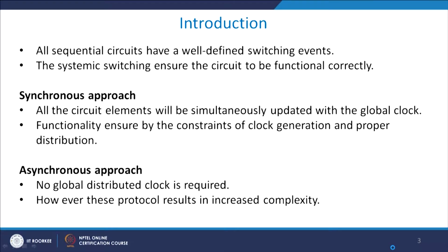As I discussed with you, all your sequential circuits have well defined switching events, which means that these switching systems ensure that the functionality of the circuit is not compromised. Let us suppose it is a positive edge triggered latch, or a positive edge triggered register, which is accepting data, and then giving it to a combinational logical block where some computation is being carried out, maybe a logical operation, and after that it is fed into another register where it is stored for a short while and then given to the output side.